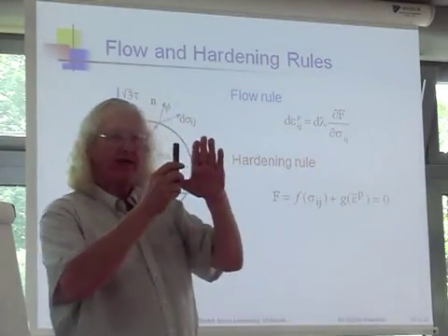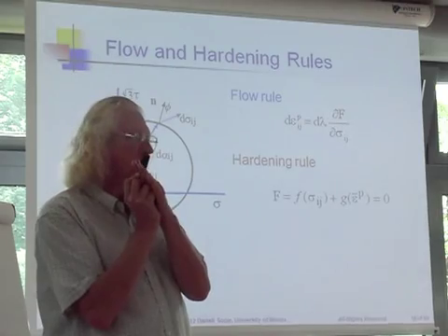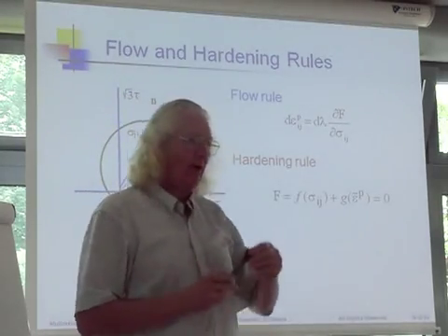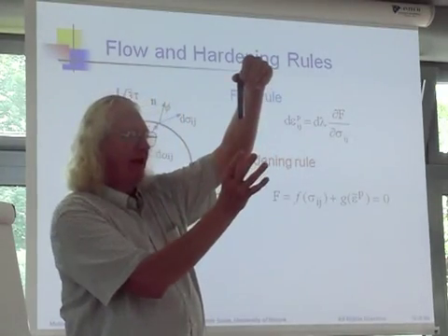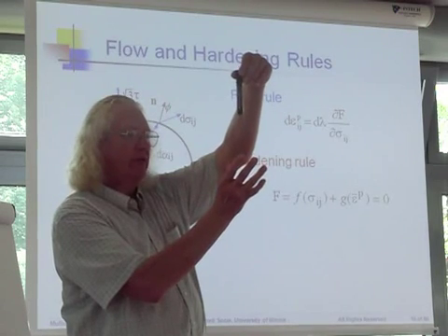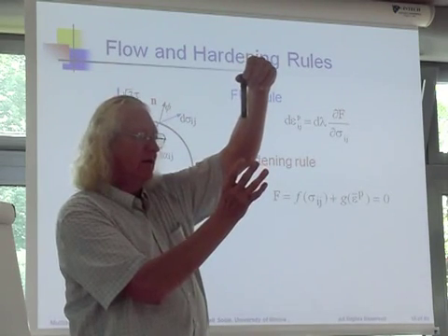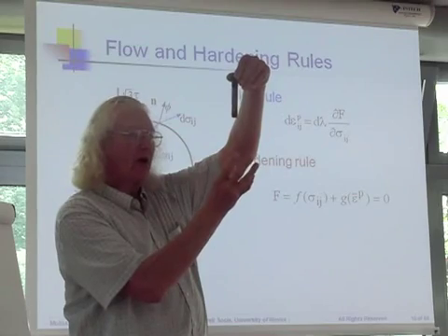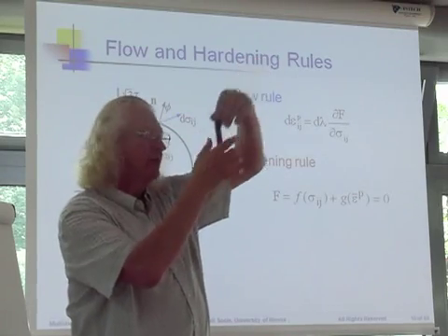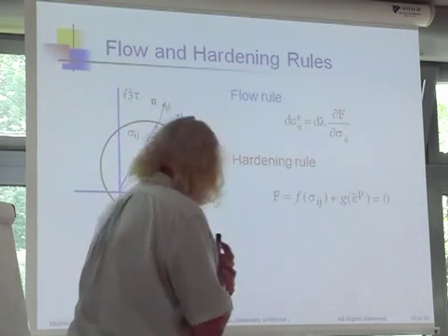Do they go in the same direction of loading? And the answer is no. Right? The answer is no. And that's my experiment. If I put a static tension on here and then I twist it a little bit, right, what happens? Well, this actually gets longer, and that's that coupling between the tension and torsion loads.